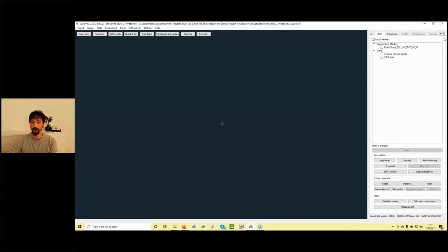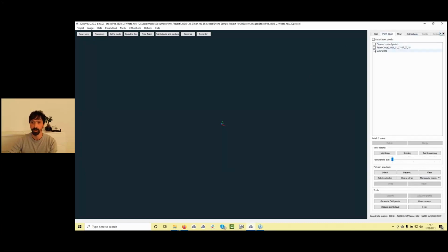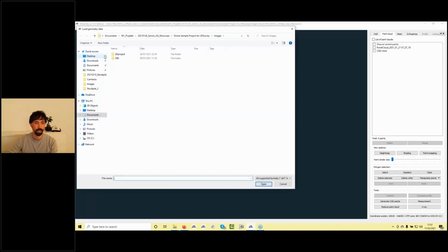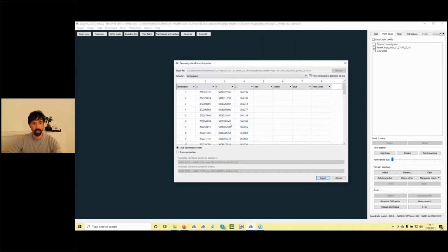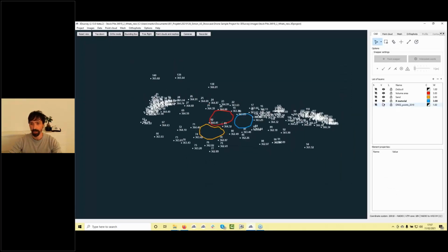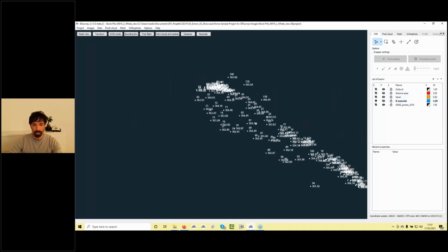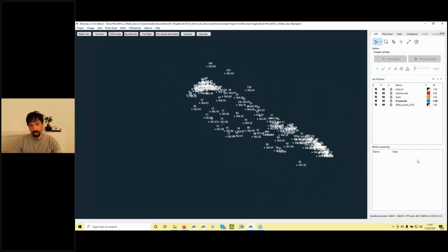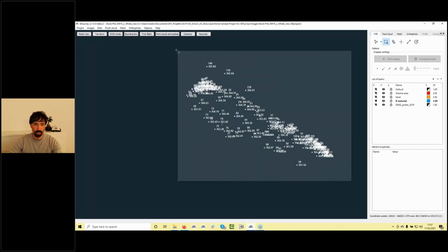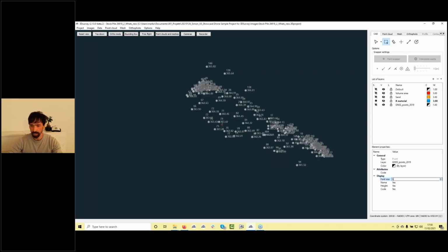So I will turn off my regular grid mesh. I will go to my point cloud. Here is the existing one, and now I will load my points which were actually measured 2 years before with the GNSS measurements. We see point name, X, Y, Z, local coordinate system, import them here, and I have them here. Let's turn all other layers down. Cool. These are my 3D points, maybe smaller. The text size, really quickly, to 6.